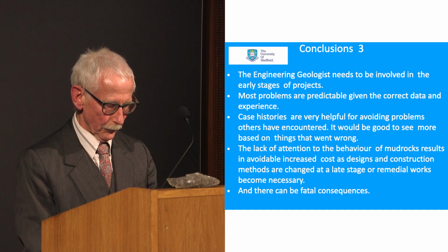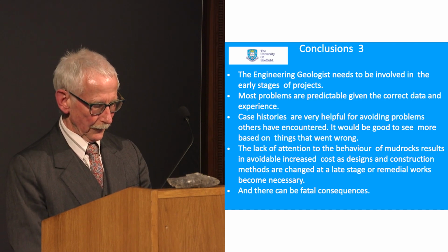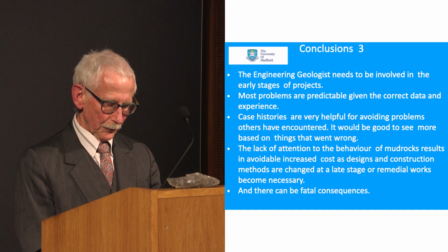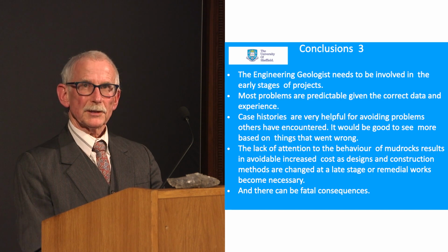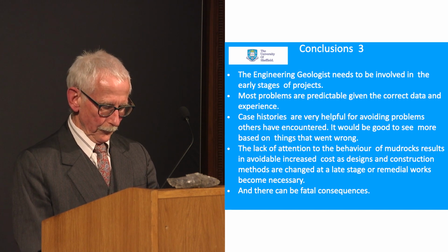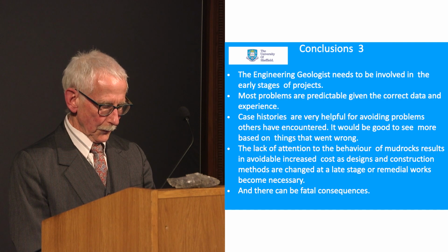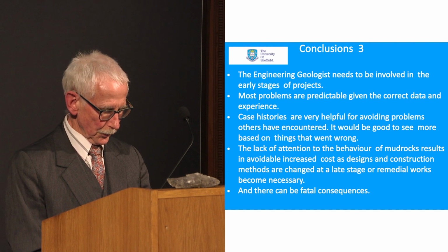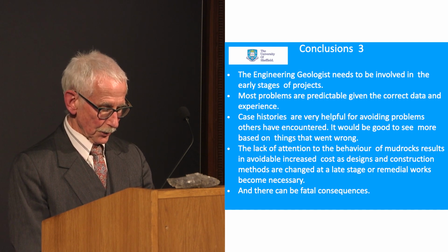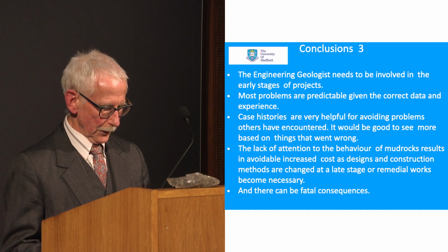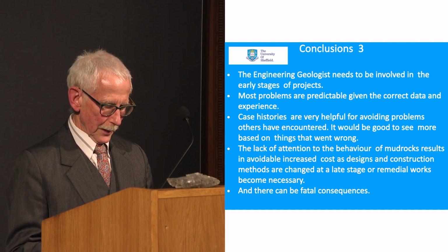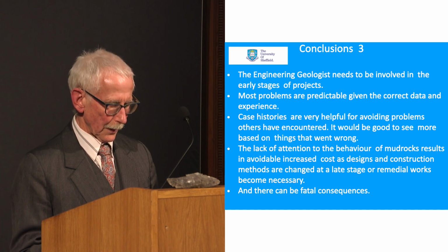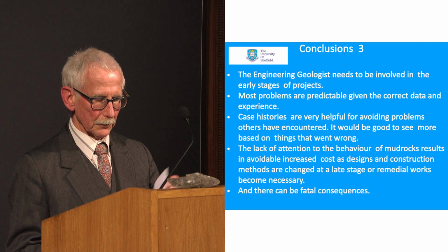You'll have heard this one before, and that is that the engineering geologist needs to be involved in the early stages of projects. Most problems are predictable, given the correct data and experience. Case histories are very helpful for avoiding problems others have encountered, and it would be good to see more based on things that went wrong, where there have been solutions. A lack of attention to the behaviour of mud rocks results in avoidable and increased cost as design and construction methods are changed at a late stage or remedial works become necessary. And, as I mentioned, there can be fatal consequences.